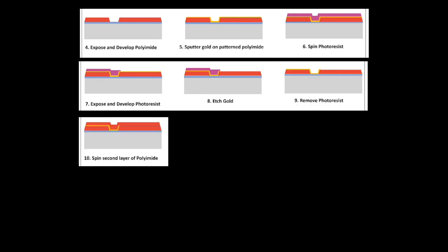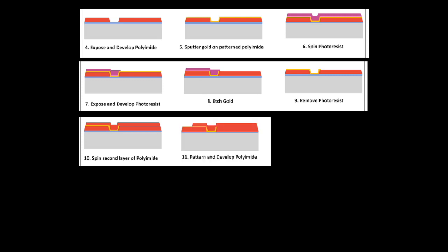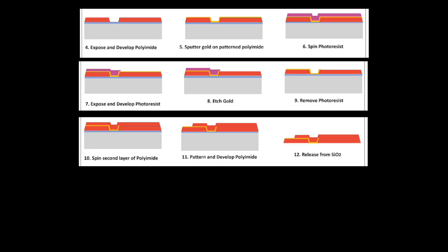After this, another layer of polyamide is applied, patterned, and removed where the gold contact is needed with a circuit board. So the finished design is like a sandwich of polyamide, gold, and then polyamide again. It's a pattern of conductive gold circuits encased in an insulation layer. Now, the finished structure can be removed from the silicon disc. The gold is exposed at one end, ready to connect to the bus of a chipboard.